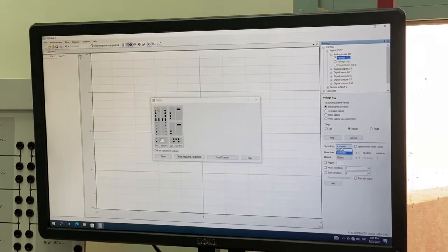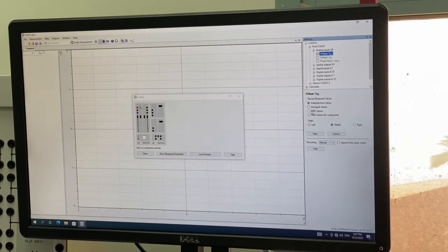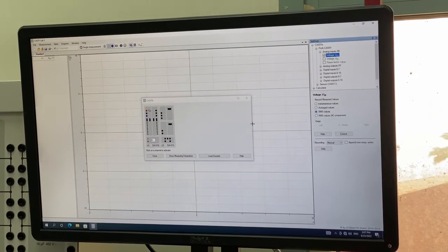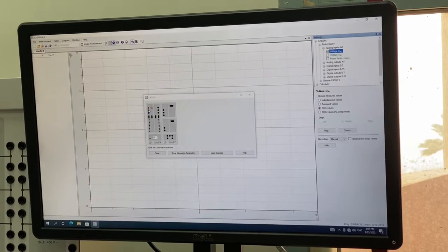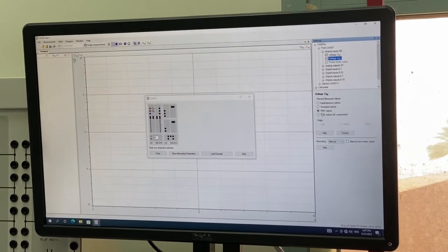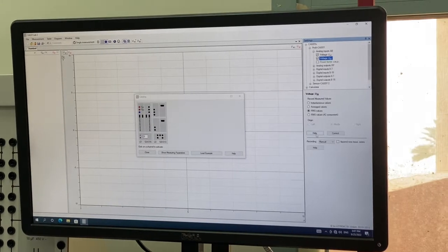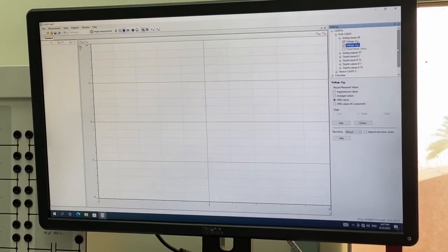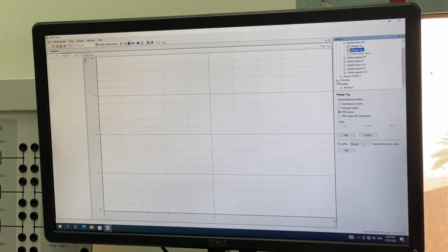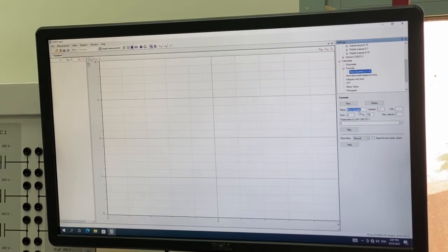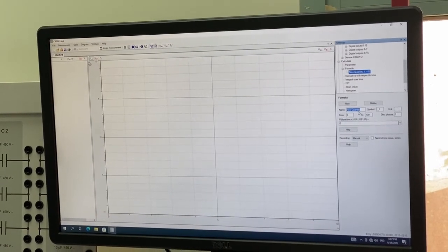You select the manual recording and select here RMS value. Why RMS? Because our supply is AC. Done. Second one is channel B. You click, it is activated, and this is RMS value, right? Okay. So now you close this one. You don't need that anymore. The second step is to define the parameters. So go to the calculator, click on the formula, new. The first 2 things you have to define are voltage and current, right?